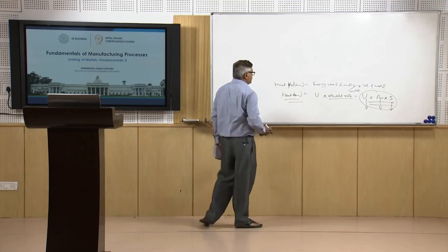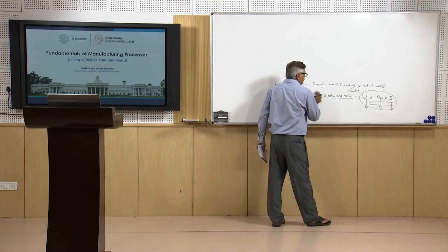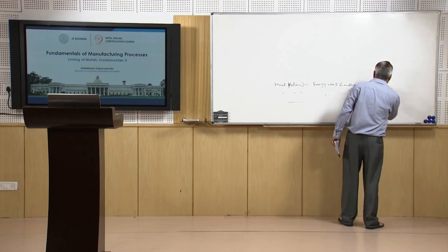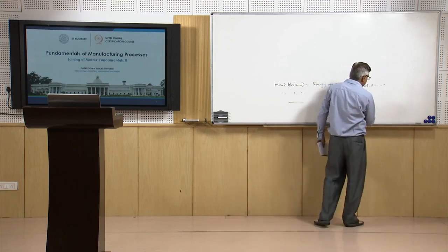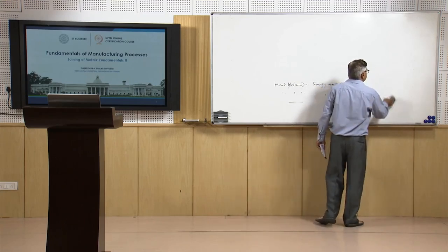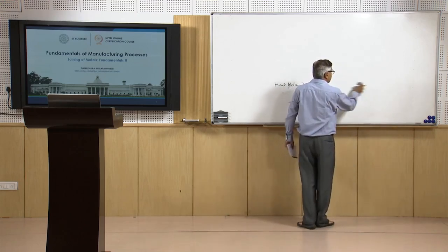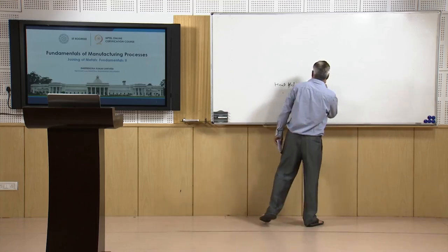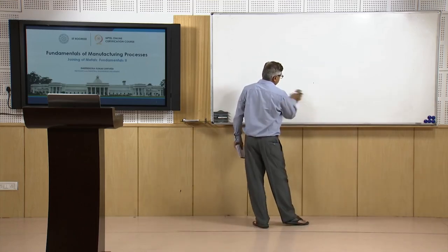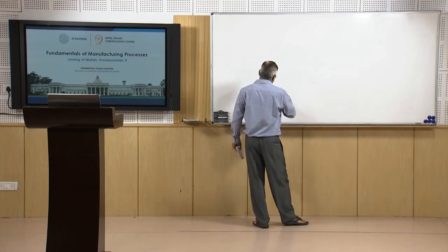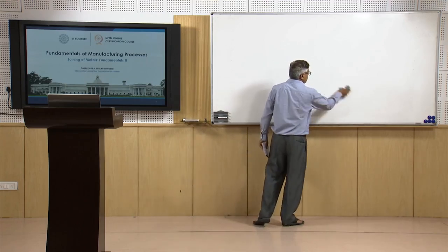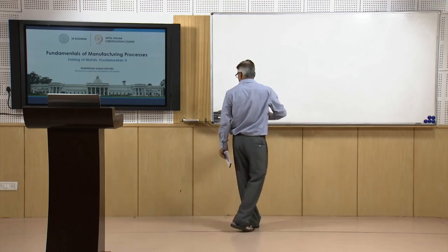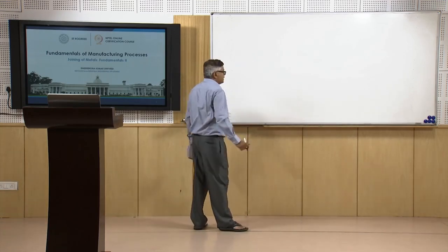This can be used. So, any one if it is not known can be determined, like the heat required for melting the unit volume of the material is a kind of property which can be obtained from the welding speed. We will be knowing the speed at which the welding is being done, and from the setting of the welding current and welding parameters, we can obtain the amount of heat which is being delivered, as well as from the thermal efficiency of the weld.